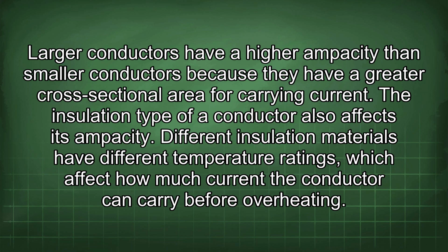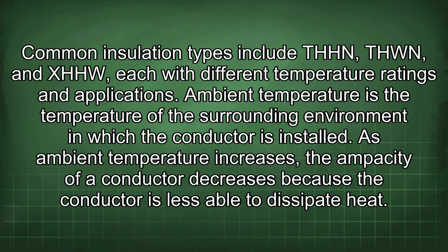Different insulation materials have different temperature ratings, which affect how much current the conductor can carry before overheating. Common insulation types include THHN, THWN, and XHHW, each with different temperature ratings and applications.